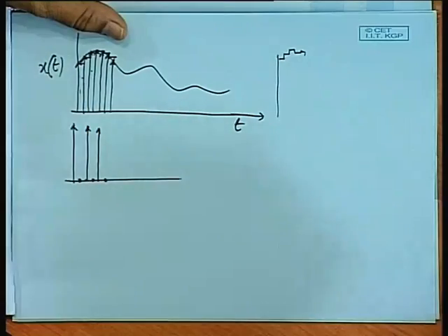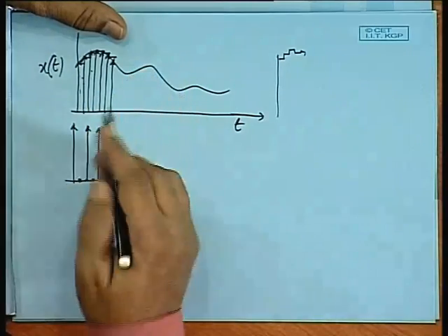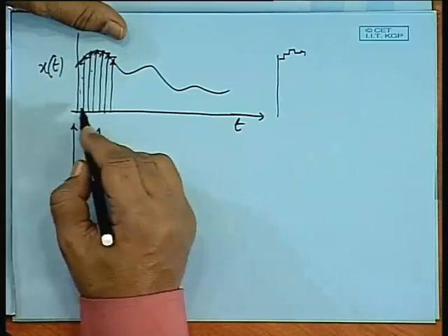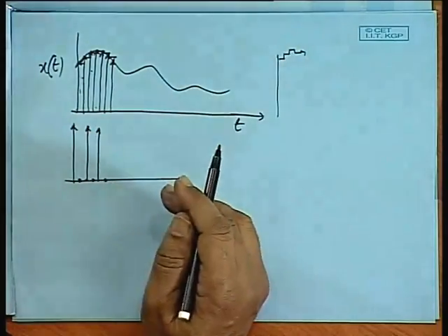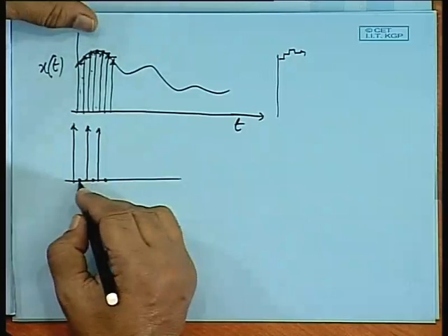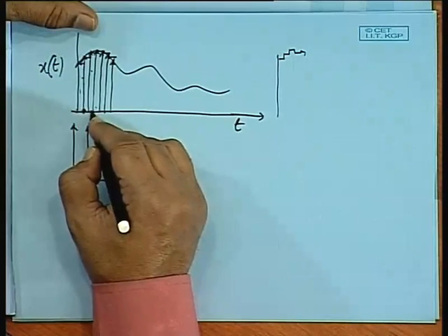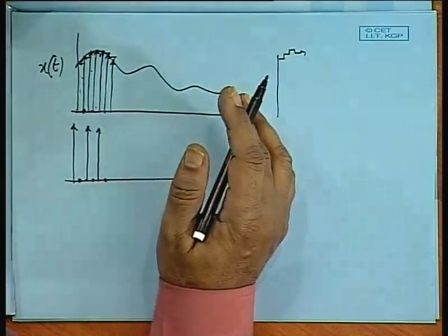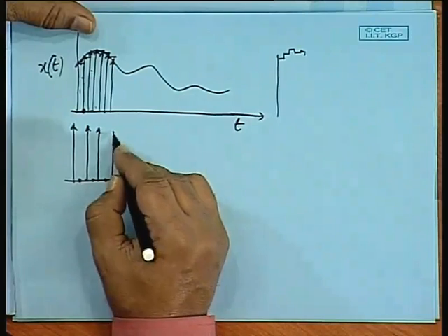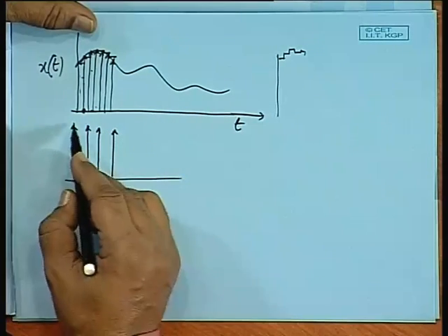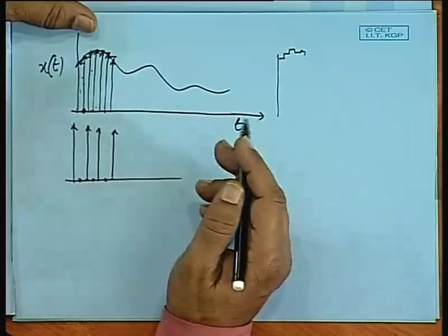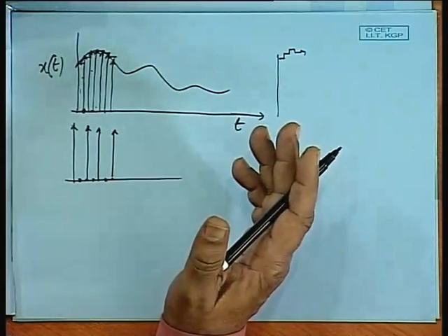Will it be the same? If the function was changing very slowly, and if I sample it at a lower rate instead of this high rate, I have these sampled values. Now I drop the values in between, that means we make them zeros. Then we get samples like this that may represent the original signal to a satisfactory level.